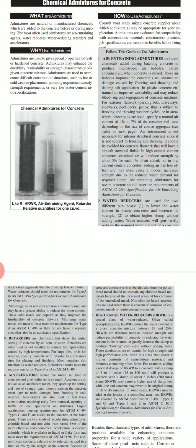The second is to obtain a higher slump without adding water. We do the slump test to check the workability of a concrete. Depending upon the slump height, the slump is a cone-like structure. Once the concrete is prepared, we form one cone structure using the slump apparatus. If the slump height is good, then we can call it good workable concrete. Depending on that slump height, we decide the slump value. If the slump value is good, then the workability of the concrete is good. We are going to study the slump test in the next highway and concrete lab.